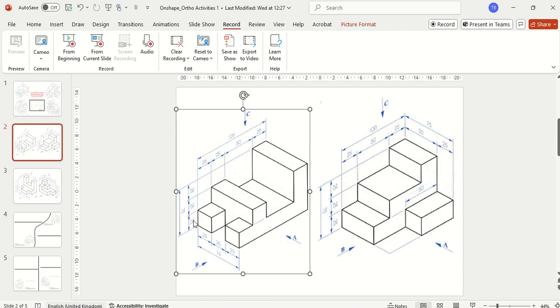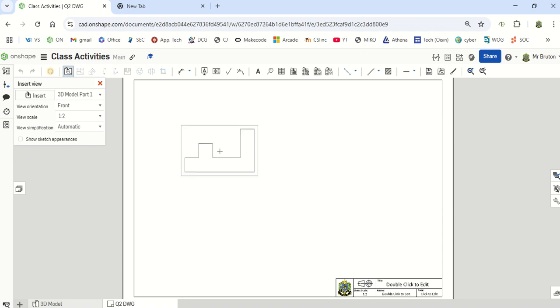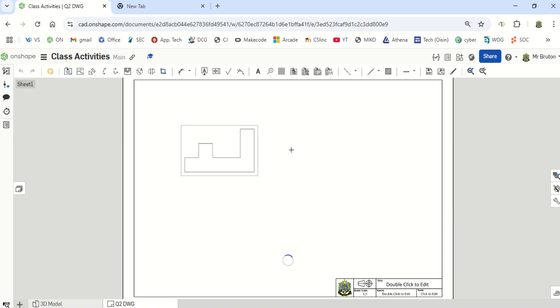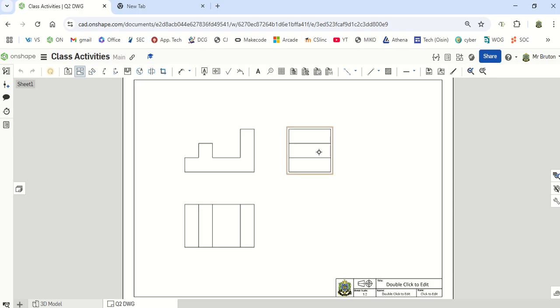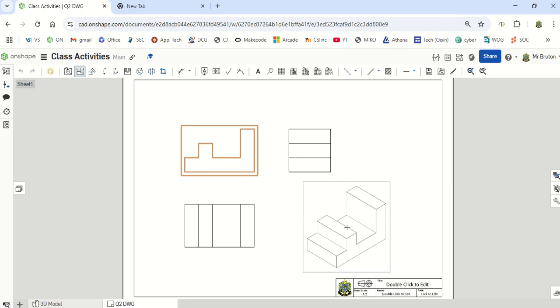if we go back to this drawing here for a second, we need to do a front view from arrow A and a side view from arrow B. So it's looking in from the left, so it gets projected on the far side. So if you're standing at arrow A, arrow B is looking in from the left, it should be drawn on the right hand side. So I'll go back here, there's arrow A, I'm going to move this over to the right, there's our end view. I'm going to click this again and move down, and that's our plan view. Sorry, that's the end view over there. This is the plan view, and I want to hit that one more time and go diagonally down, and there's our 3D view.